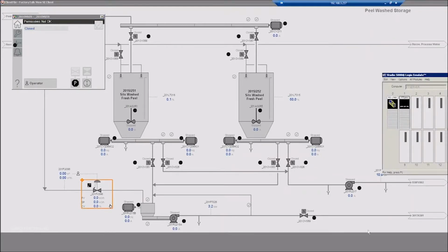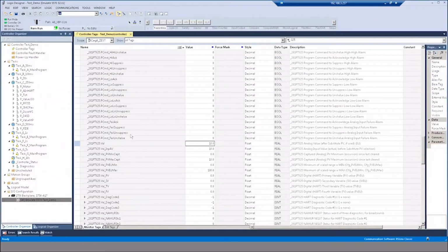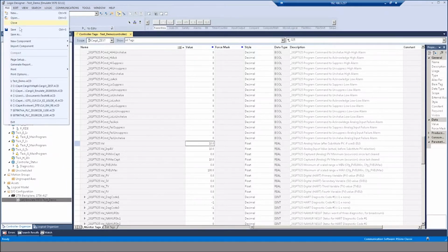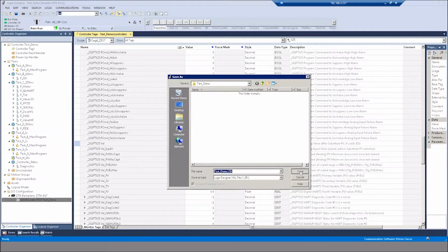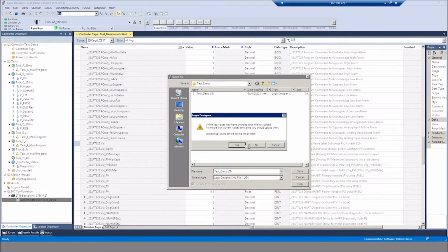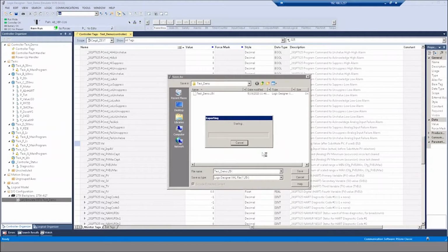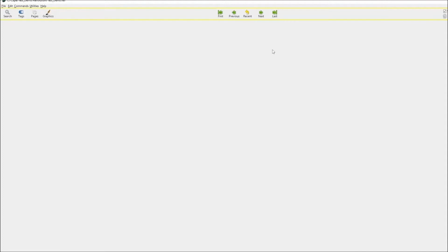For this example, the process we will be looking at today is a simple Rockwell system with an HMI screen and one emulated controller. In order to be able to establish communication between VPLink and the Rockwell controller, we need to extract the I/O tags from the controller and download them to the VPLink program. This process of extraction shown in this demo is similar for other control systems. VPLink has various extraction tools for different control systems, making it easy for users to test their various system components.